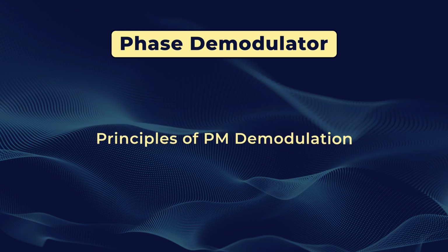In this, we are going to see the principle of the phase demodulation process. There is a very important component in phase demodulation, that is a PLL based phase demodulator followed by an integrator. It is a sophisticated method used to demodulate the phase modulated signal. This method is widely used to lock on the phase of the incoming signal and then use an integrator to recover the original modulating signal.